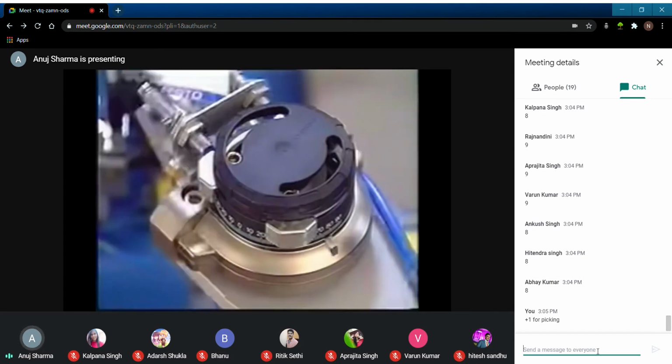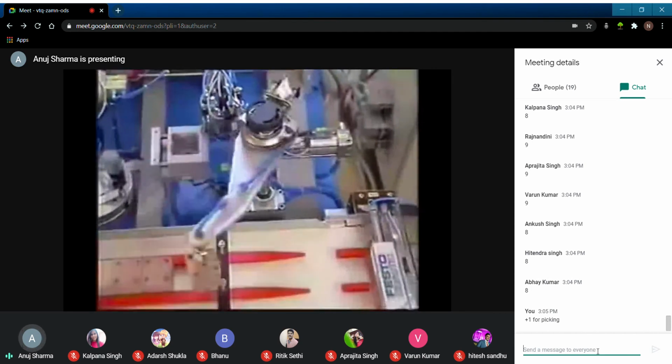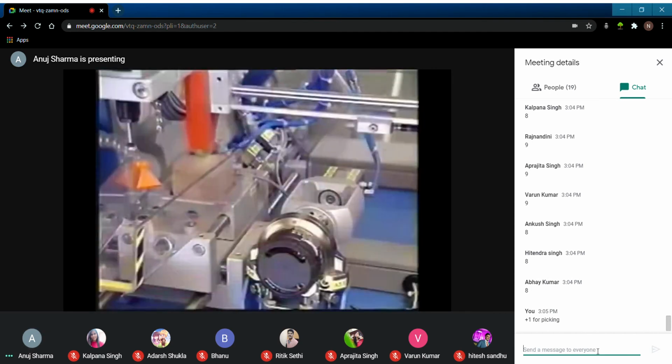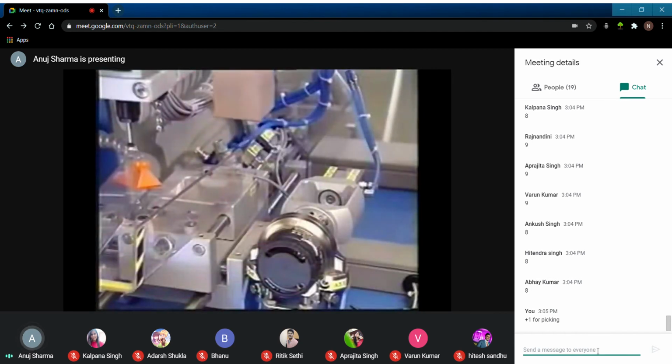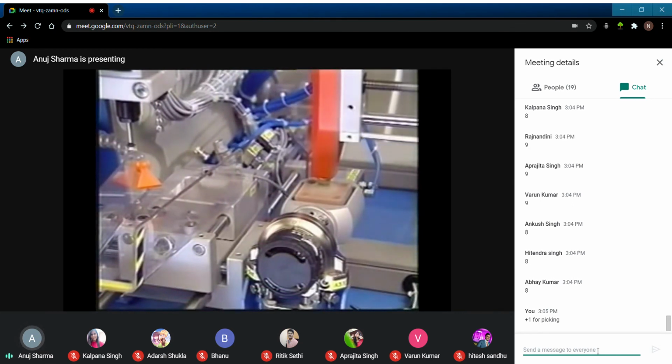Rotary cylinders can be used in a number of applications. In this example, it's moving parts from a test station to a conveyor belt. Another use is for parts orientation. Here, a rotary vane cylinder is used to turn parts over for machining on the opposite side.